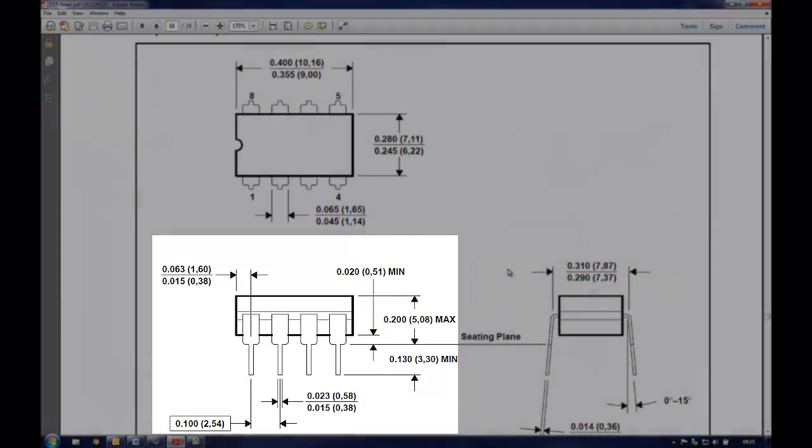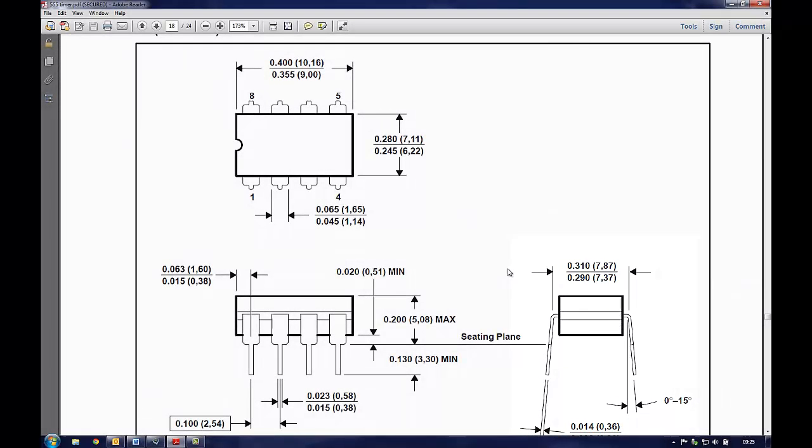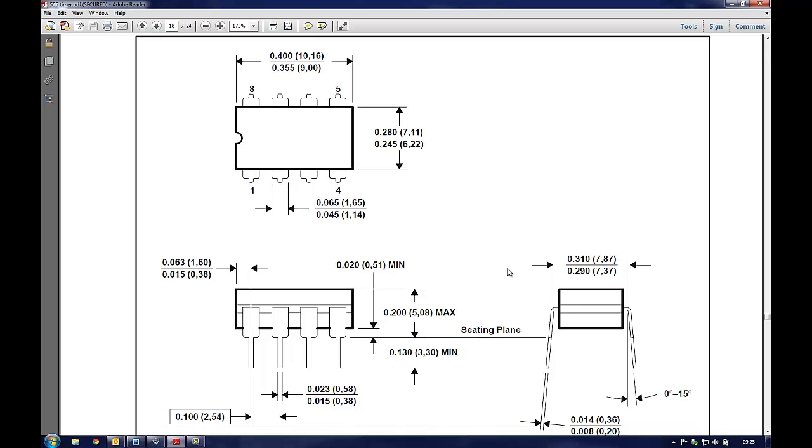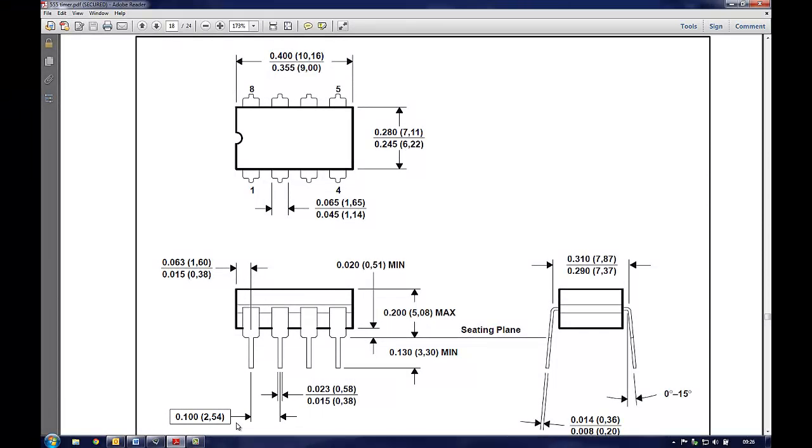The user needs to pay very close attention to the tolerances and design the component footprint to accommodate the biggest possible dimension where appropriate. For instance, it is important to make the physical length and width of the component big enough to accommodate the biggest dimensions with regards to tolerance. However, the pin should always be the median of the tolerances, as pins can usually bend from the median point to fit the minimum or maximum hole spacing.